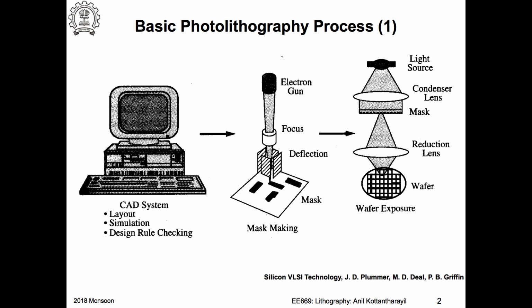So what happens in this case is that the chemical would go through some transformations, typically polymerization reactions, or maybe some polymers will be broken down. So there are different types of resist, and I'm going to expose. I have this photoresist deposited on the entire glass plate. On the side where you have the chrome, or iron oxide, you deposit the resist.